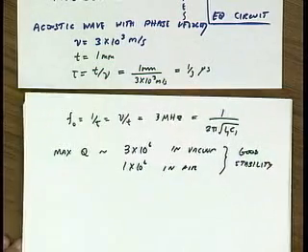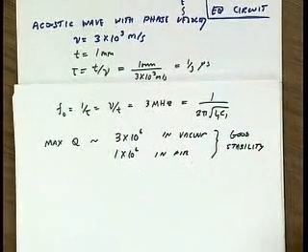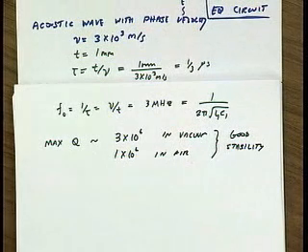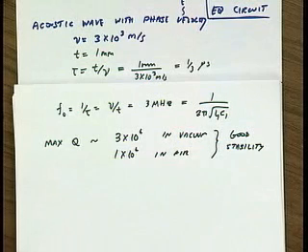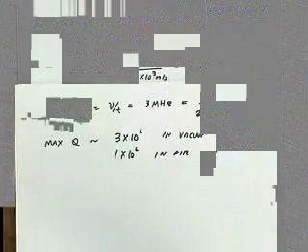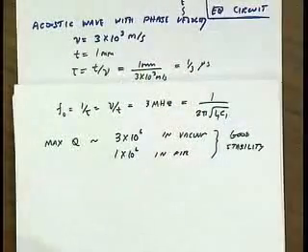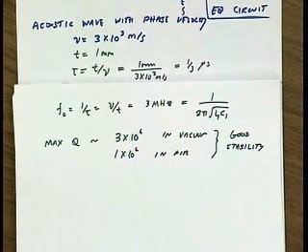And if you think about our discussion last lecture where we discussed phase noise, we found that phase noise was inversely proportional to Q squared. So obviously the way to design a very stable reference with good spectral purity, one brute force method, is to use the highest quality factor tank that you can. And you cannot build purely electrical resonators approaching 1 million quality factor. You have to in fact use mechanical resonators.